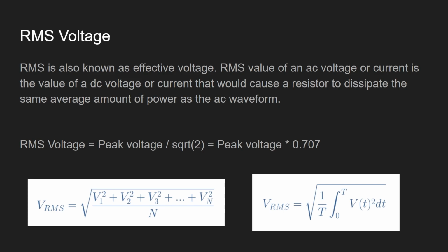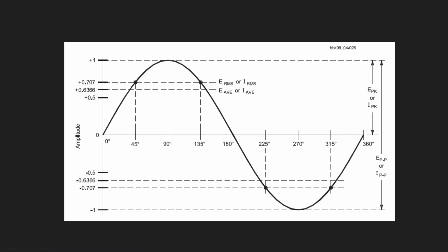So we want to compare the effective voltage of AC with DC. If you have a chance to measure AC with a multimeter, you have to flip your meter to measure AC. If you measure it wrongly, you may read the peak value. You can just multiply 220 by root 2, which is 340 something, as I remember. So you may read a value like 340 something. That is the peak value, so you did it wrongly.